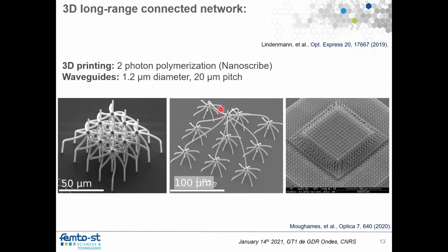And we've explored here different degrees of connectivity, where here every input connects to 9 outputs, here every input connects to 81. And here we have basically realized a complex network connecting more than 200 input channels to, I think, over 500 output channels. And here you see the power of the 3D integration. You could never implement such a thing in 2D, considering the feature size, because it would essentially take the size of an entire desktop.